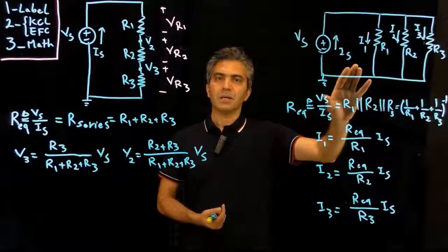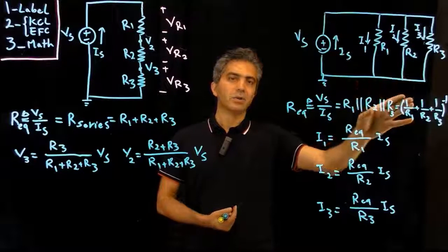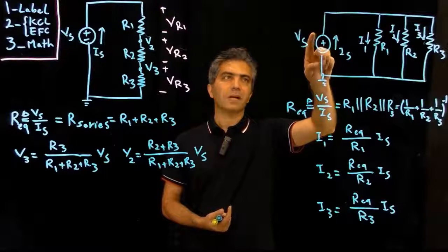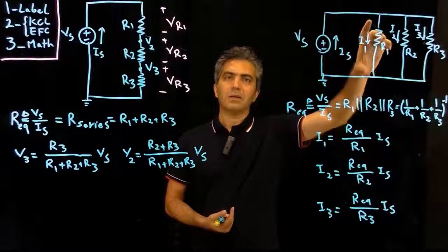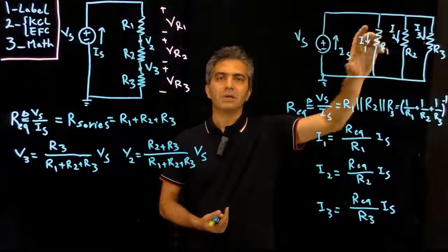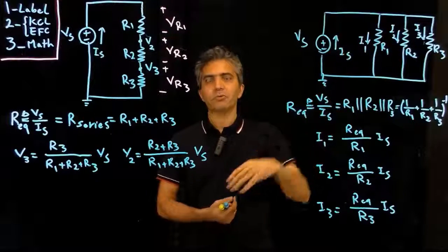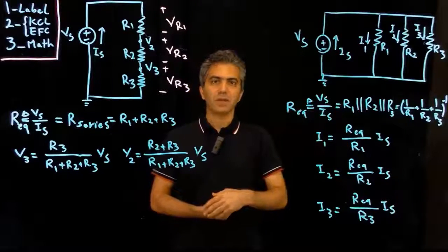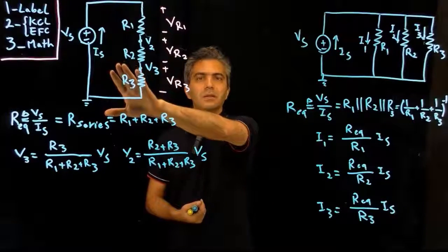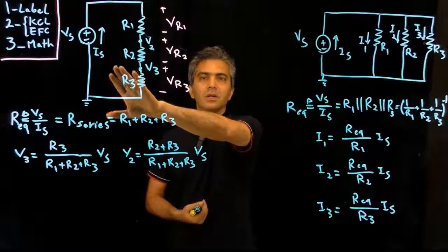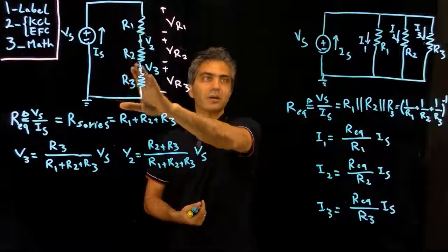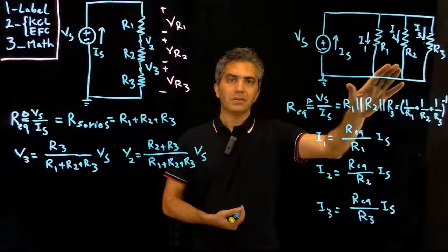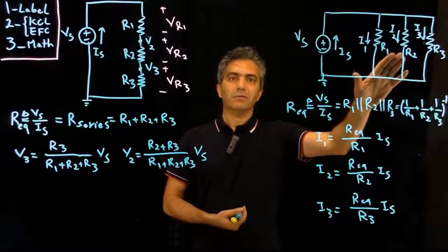And then we also did the same thing, calculated equivalent resistance, and basically analyzed the circuit for a situation where the resistors were set to be in parallel to each other, and that situation was defined as when the two resistors share the same node on both terminals. In other words, they share the same voltage across them. So in the series situation, the resistors share the same exact current. In this parallel situation, they share the same exact voltage.